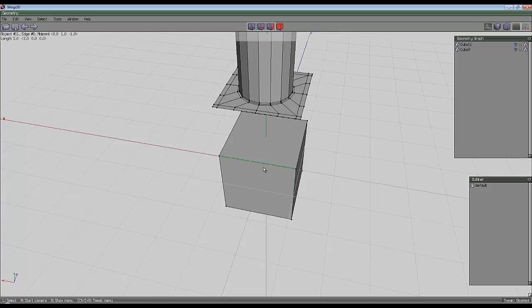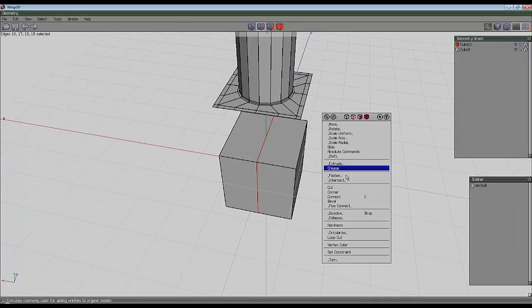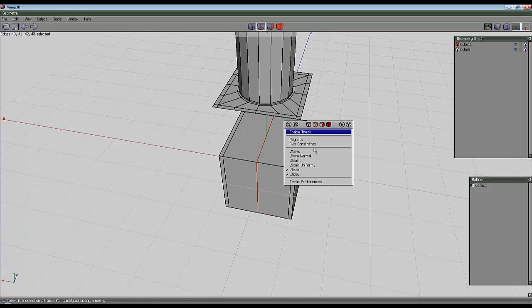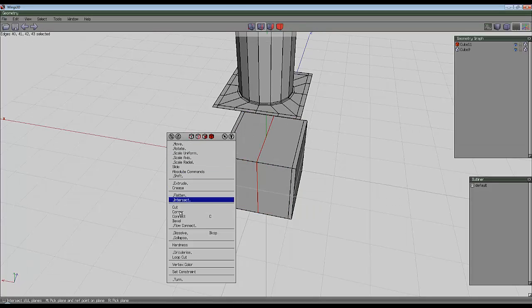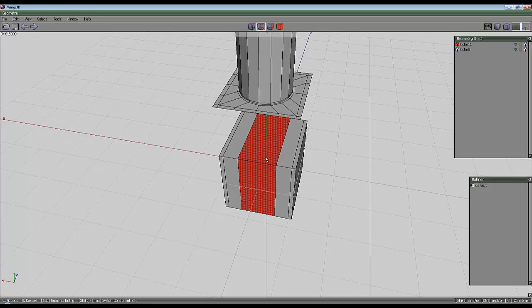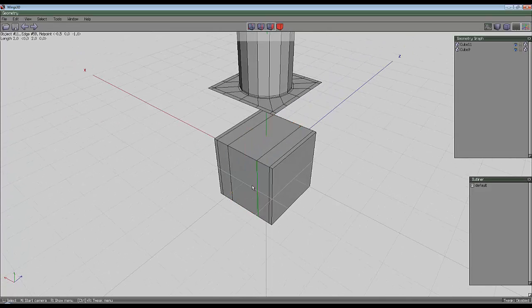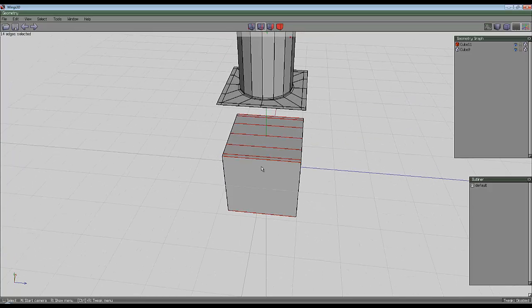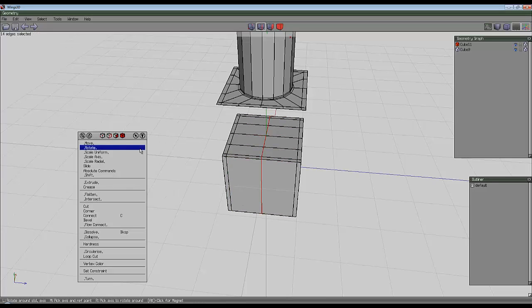So to sort that out, what I need to do is carve this one, so G and C, up in the same way as I did the last one, which will take a few moments but isn't very difficult. So I just need to remember to bevel this the same amount, so that was 0.5, the figures there on the left, and that's one lot. So it's G, C, and bevel it out to the edge, holding the shift key down, control key down, giving me exact values, which is good.